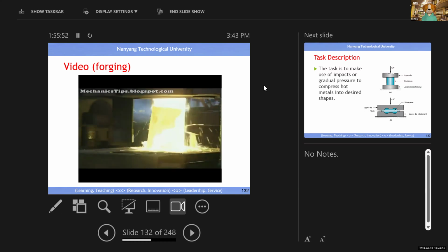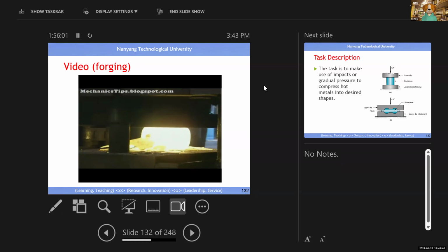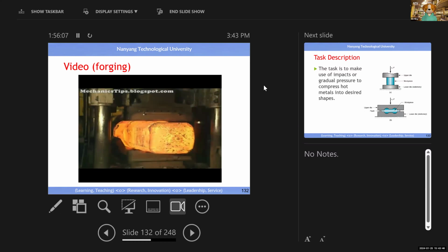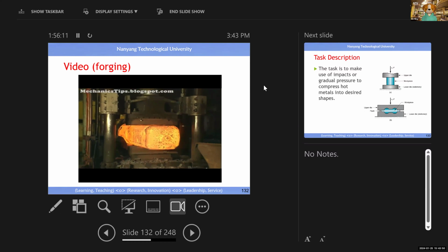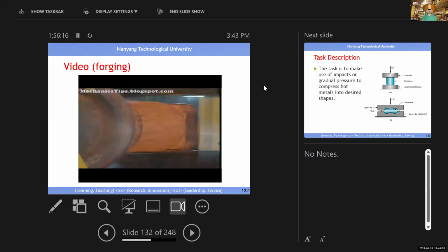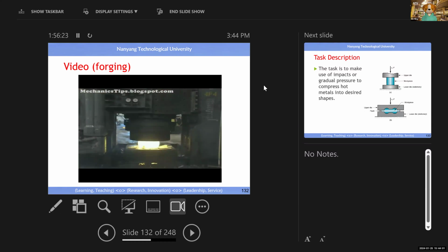Open die forging is performed on ingot, billet, bar, or a preform, and is the deformation of a workpiece between flat or shaped dies without completely restricting metal flow. This deformation can result in lengthening of the workpiece while reducing its cross section. Upsetting increases regions along the length to greater sizes than adjacent regions. See the change of bulging the workpiece's cross section while reducing its length.